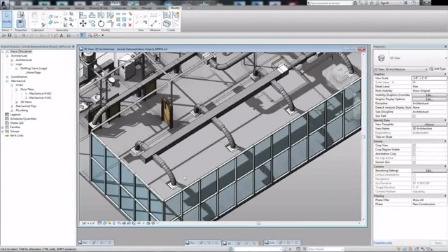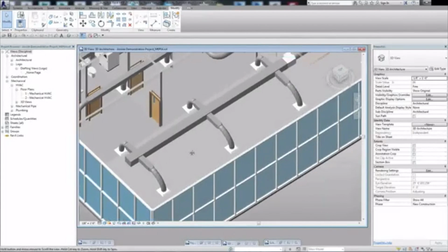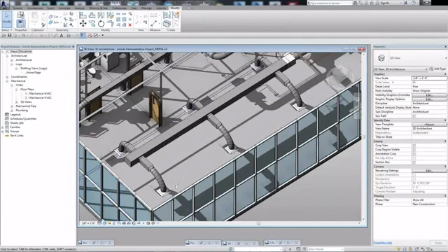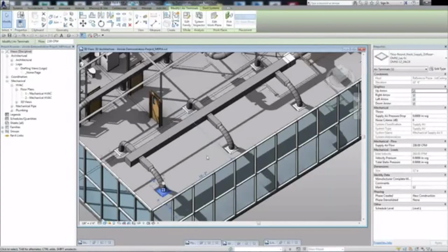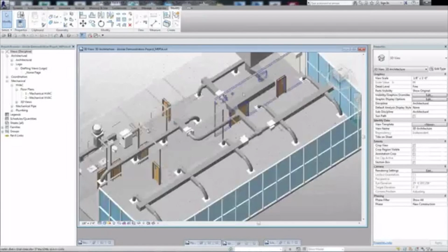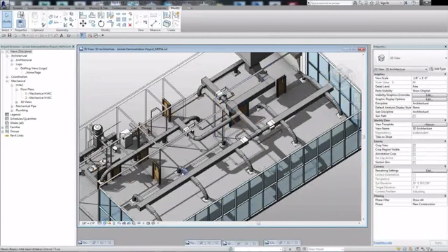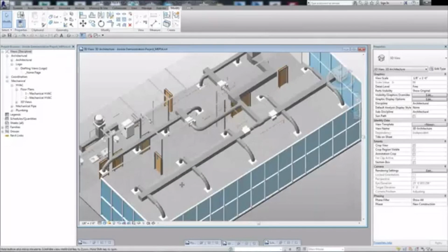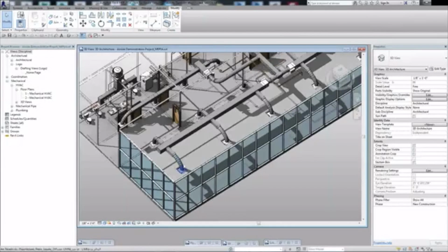primarily the reason why engineers like to use it is because of the flows, the ability to sum the total flows for a space. They're going to do their calculations on the size of the space, but when they start figuring the loads and sizing the duct, a lot of that can almost be automatic through Revit. So it all starts with the flows. In Revit, the flow data actually travels in the opposite direction of the media. What I mean by that is that the airflow in this case is going to start at the air handling unit, come down through the branches, through the VAV boxes, and be distributed out to the diffusers. Well, the flow of data in Revit is actually in the opposite direction.